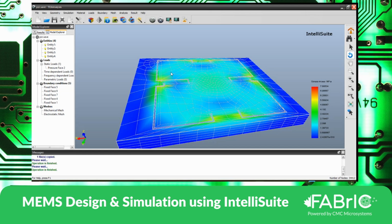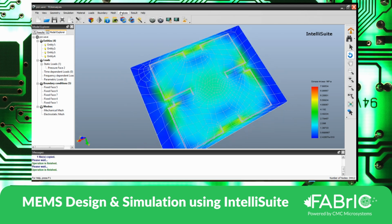In such situations, the software can take care of such unknown stuff by itself, and then produces this kind of profile. So when the piezo resistors are deformed, their resistivity will change. Due to the change in resistivity, there is a change in voltage drop. Okay, so the same principle of Wheatstone network is applied here.